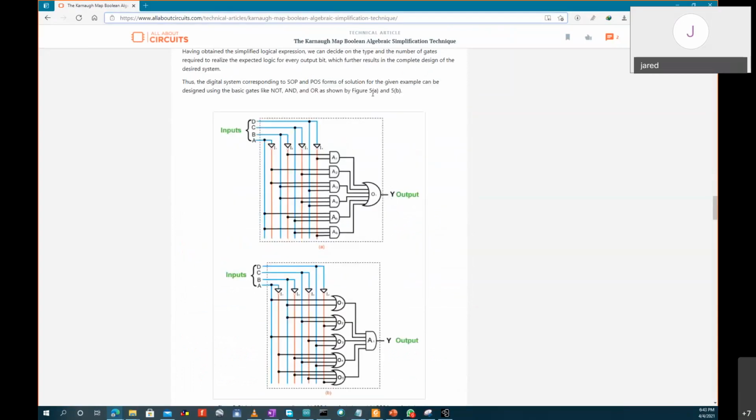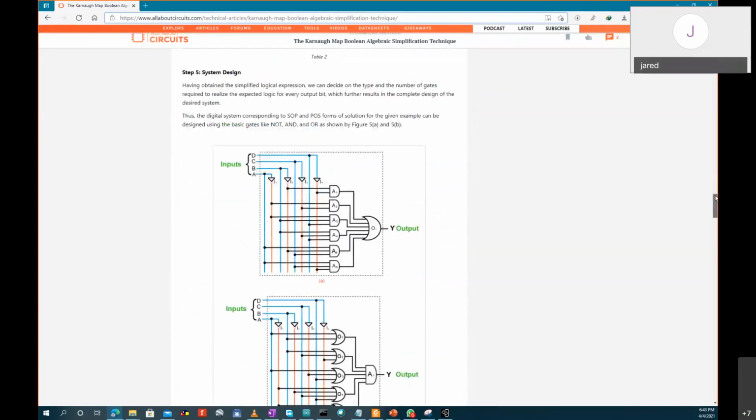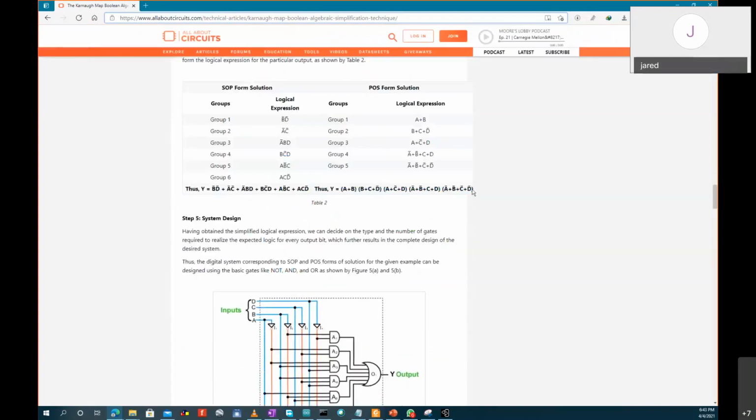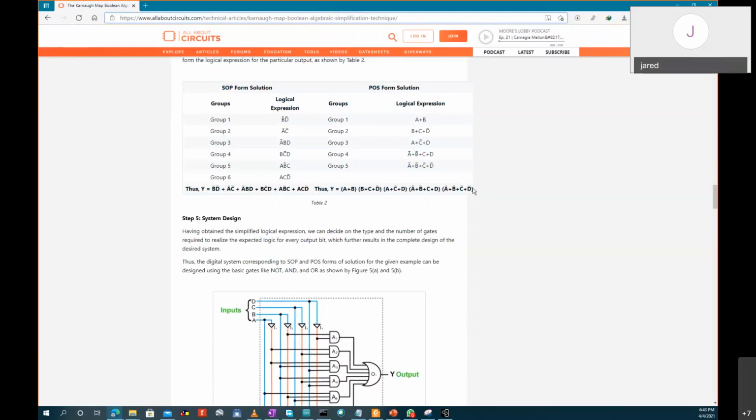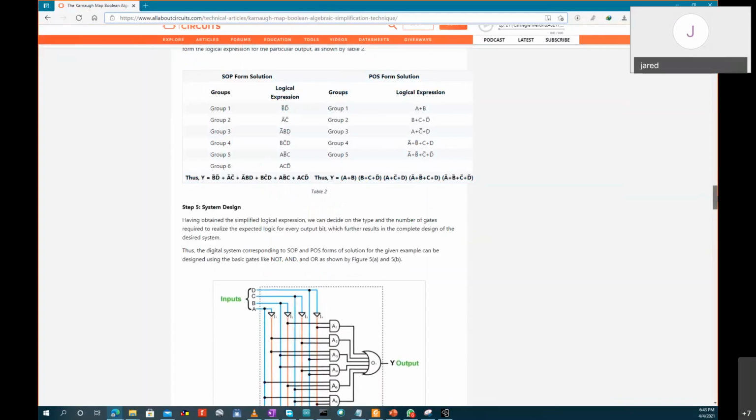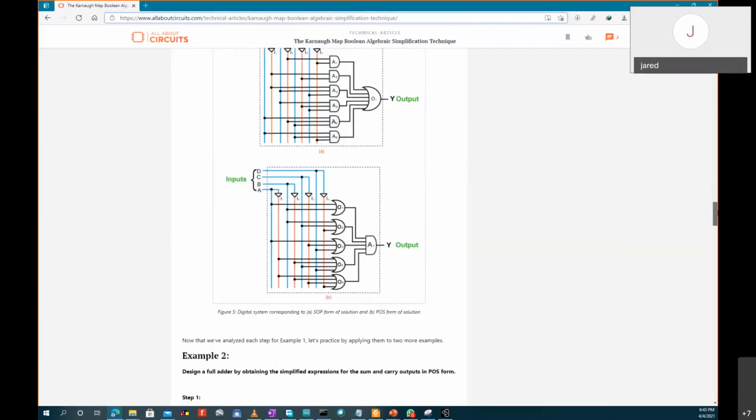And this is what basically you'll just pick from here. You pick it directly to your PLC logic. You put your A, B, C, and your Q. Maybe your Y is your Q1 or relay 1 or pump 1. So depending on the state of the sensors, the sensors are like A, B, C, D. Depending on the state of the sensors, what you want to achieve, that's what you get.